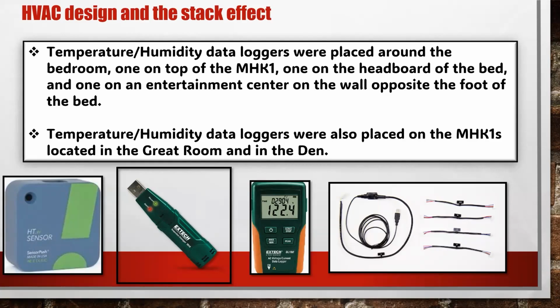Gotcha. But the unit's going to suffer because it's going to protect itself differently. We'll start trying to get the compressor to slow down. But there's a limit to how far we can slow down, so it can create other issues that you're going to have to deal with.